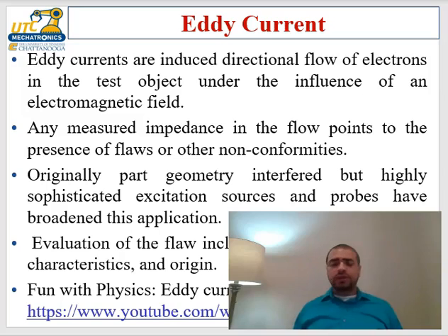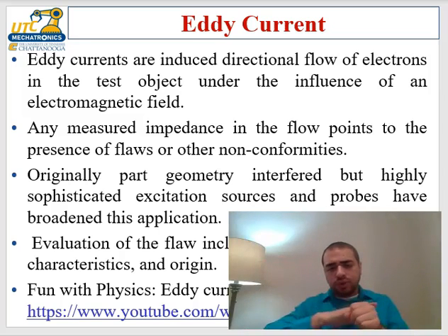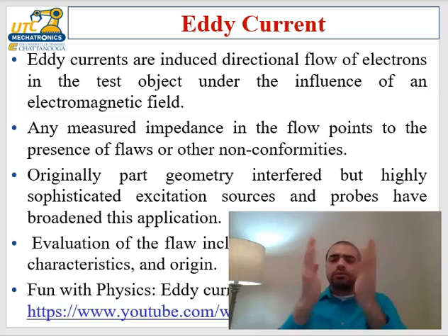That's why, for example, if you look at antennas, you will see the antenna is hollow on the inside. The reason is that there's no need to make a solid bar, because the current distributes on the outer surface. The higher the frequency is, you don't need complete metal bars, you only need hollow conductors, to make them cheaper and lower in weight. Conductors that are used for high frequencies are hollow.